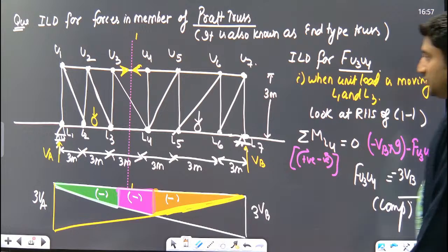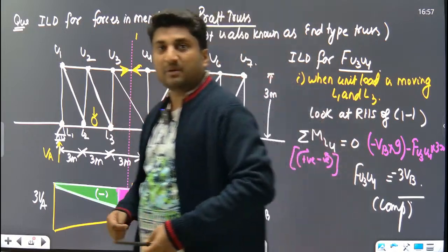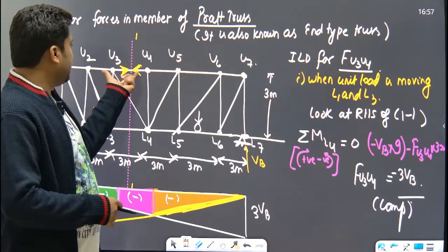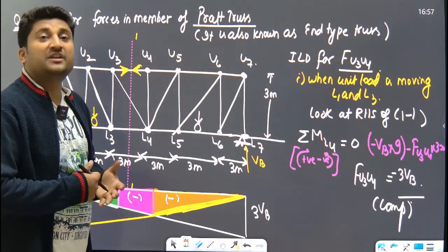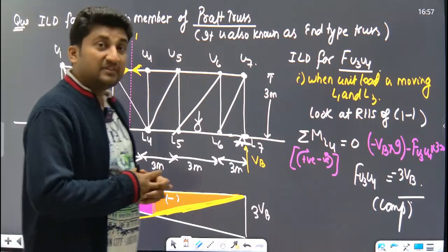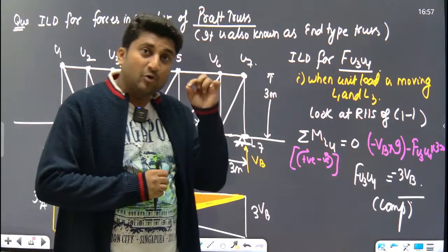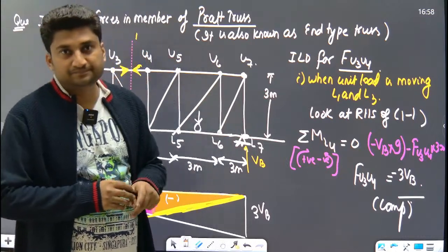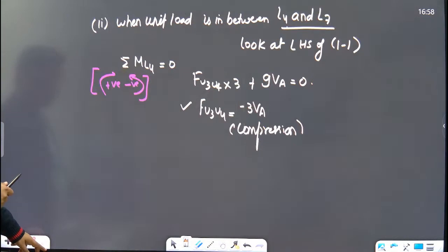Now in steel structure, you must have studied what is the maximum slenderness ratio for a pure compression member. Since this is a steel member, and this is a pure compression member, what is the maximum slenderness ratio? That is 300. And when a member is pure tension, the maximum slenderness ratio is 400. Understood? Understood everyone?